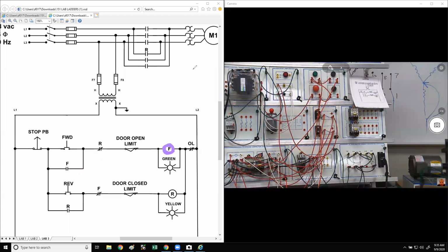It's not necessarily that the motor's not running, okay? That could be your first symptom, but there could be 100 different things telling you that the motor's not running. It could be any one of these contacts. It could be fuses. That's why it's telling you to isolate the one area of the ladder diagram that could only cause that one problem.